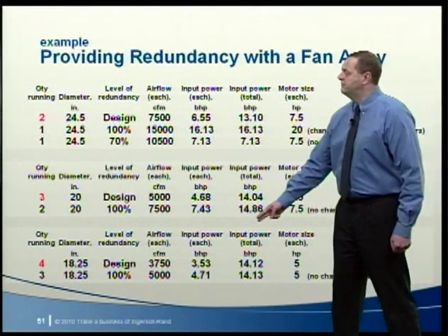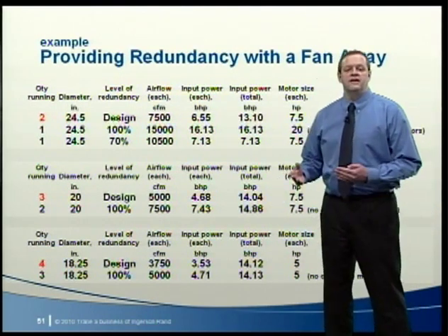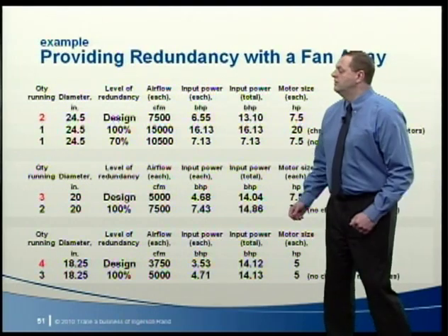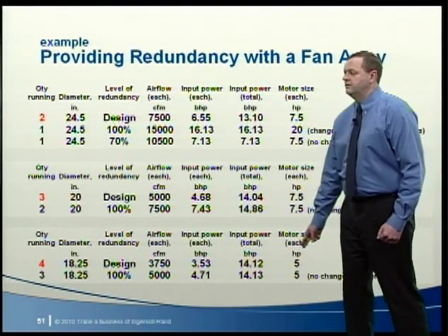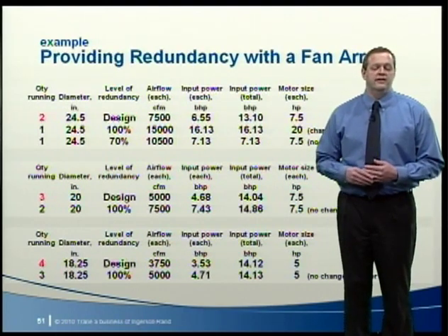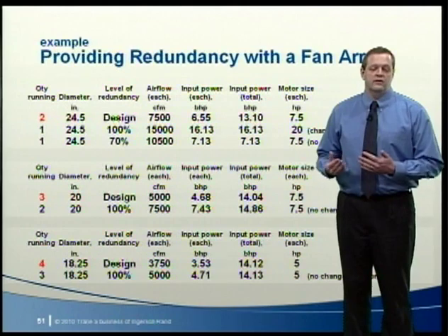The same is true for the 4-fan array. If any one of the fans was to fail, the remaining three fans could deliver the designed supply airflow without needing to upsize the motors. So for this example, if 100% redundancy is required, any of these configurations can work.